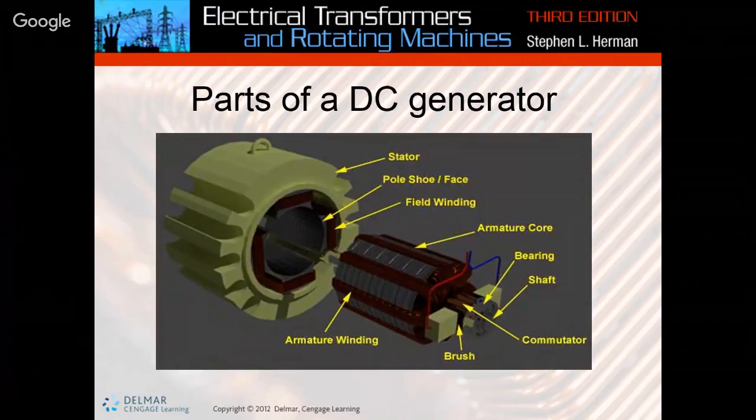The stator is an AC motor term that they just grabbed for that, but I'm just going to call it a frame. That's typically what I call them. That field pole right here, pay attention to where that is, and I'll explain stuff to you in the following slides. Field windings are going to be located inside here in the core. Armature, this big part here, this is the armature winding.